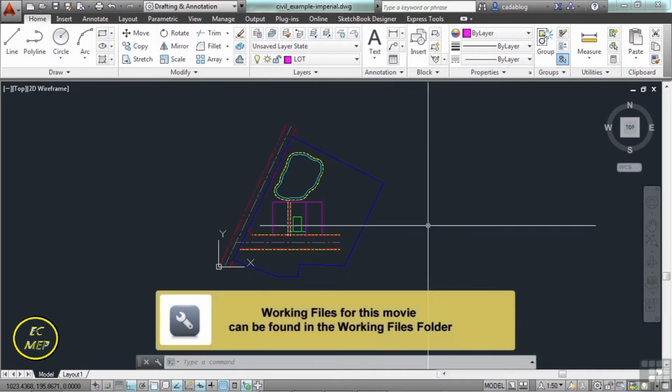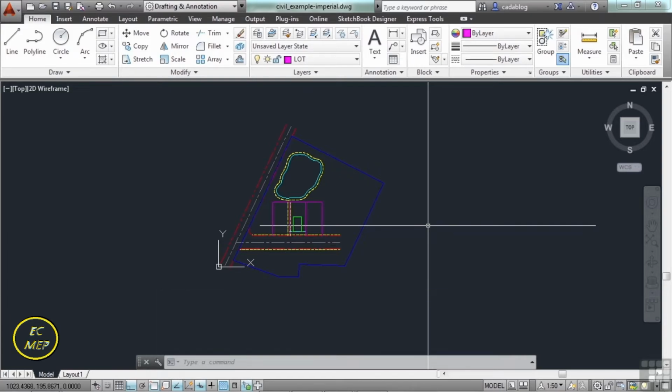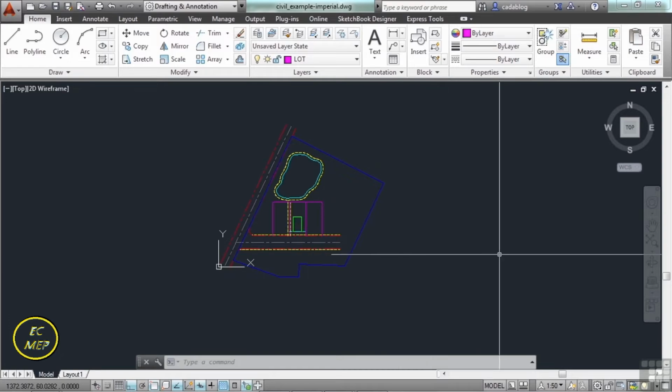By default, AutoCAD sets up the UCS in a world coordinate system. That means that the origin is at coordinates 0, 0, 0, a 0 for each axis. In AutoCAD LT, there are only 2, X and Y. So it sets up the origin at those coordinates of 0, 0, and angles facing east, or to the right of your screen, start at 0 degrees.